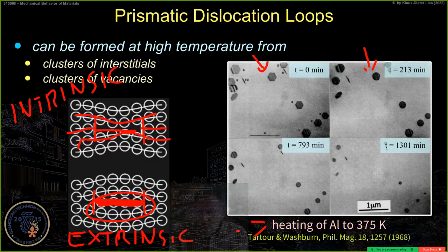Here you see, just interpret this, because we have diffusion and this is climb again. So if here we have an intrinsic loop, you can condensate extra atoms there, so the loop becomes smaller and smaller. And this is annealing. This is annealing of material. You know, when you anneal material, most of the time it becomes more like a perfect crystal. You remove not dislocations, you remove generally defects by annealing a crystal.